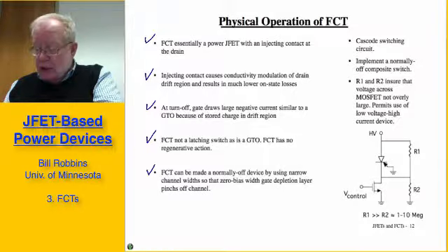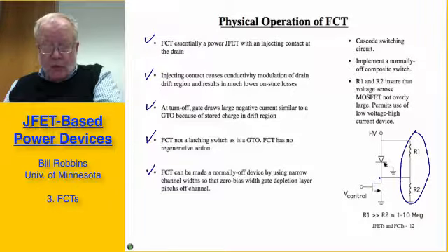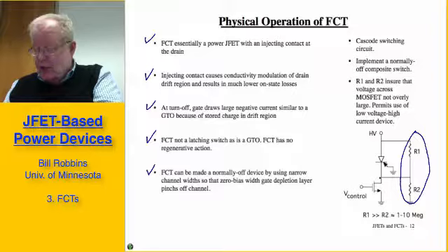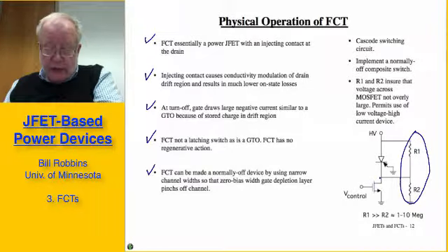That allows the voltage of the cathode to rise above ground, probably significantly higher than the gate voltage, which is at 0. To keep the voltage across the MOSFET from getting too large, we use a voltage divider, as I've indicated here, so that we keep the drain to source voltage and hence the cathode to ground voltage under control. We would typically like to use a low voltage high current MOSFET, so we're talking about probably no more than a 50 or 100 volt rated MOSFET. To avoid large currents flowing down here, the resistors R1 and R2 would probably be in the megohm range or more.